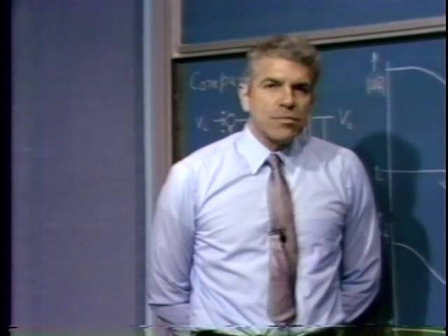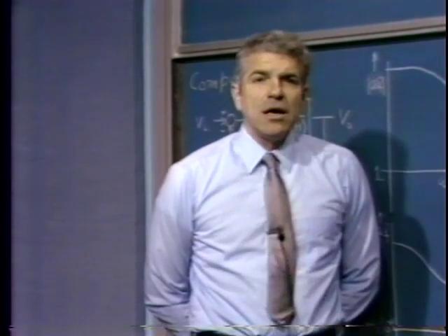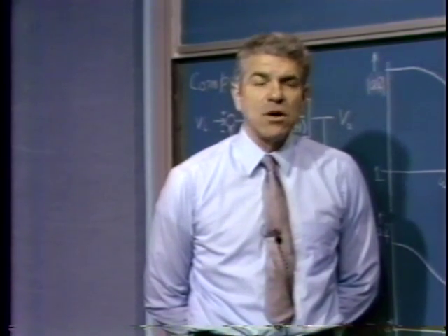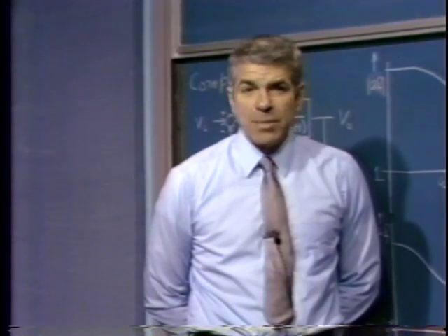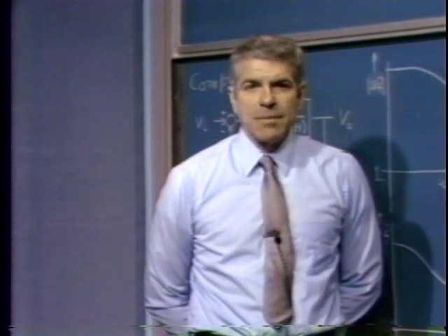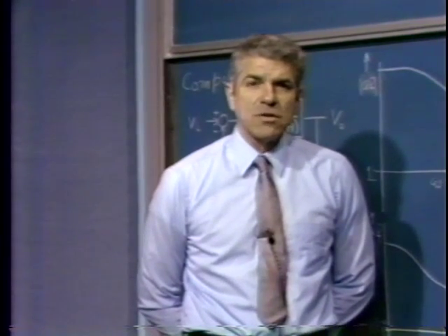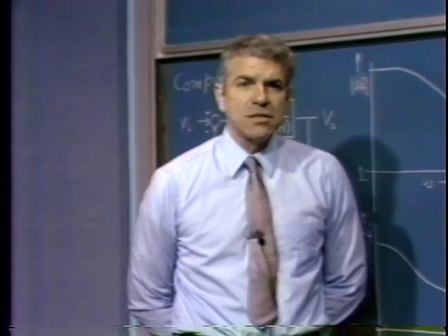these quantities. In general, the speed of response of the system scales directly with crossover frequency. Assuming we can maintain equivalent values of gain margin and phase margin for two systems that have different crossover frequencies, any measure of the dynamics of those systems, the half-power frequency, the rise time in response to a step, any of those sorts of measures of speed of response will scale directly with crossover frequency. A higher crossover frequency, of course, corresponds to a wider bandwidth system, a faster rise time system.